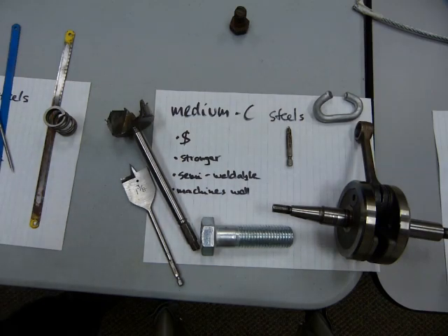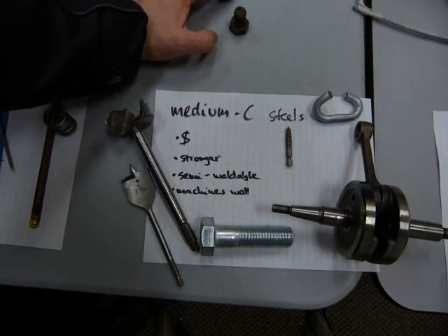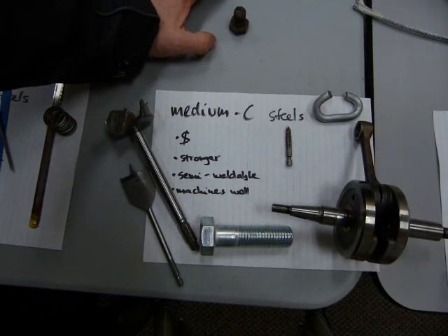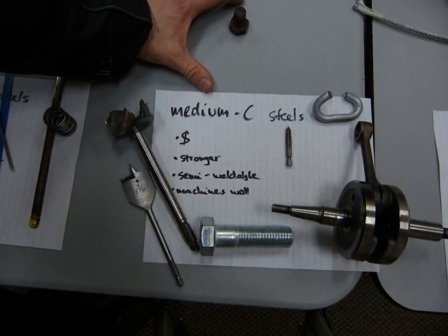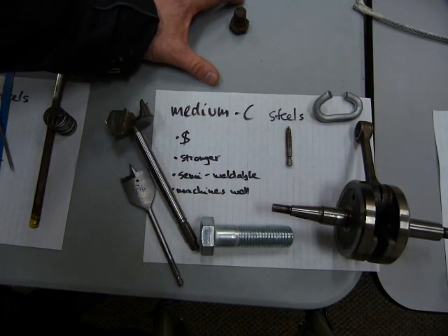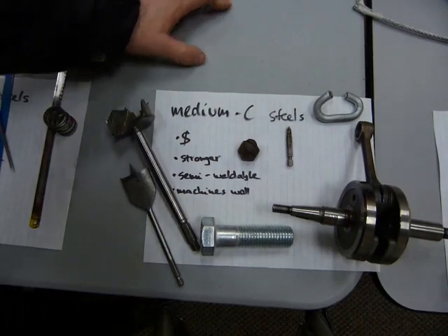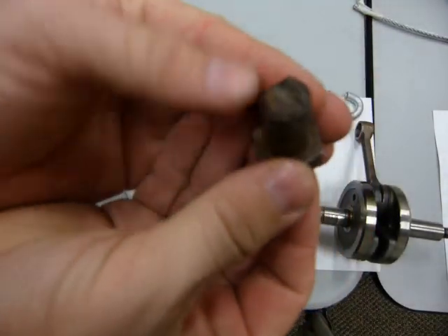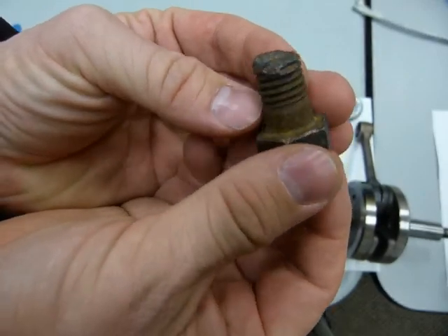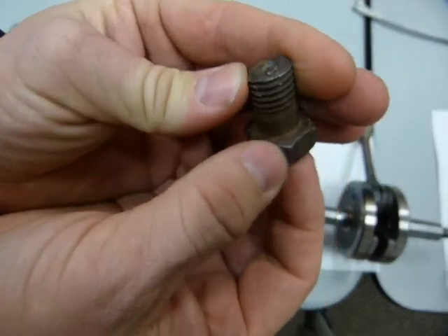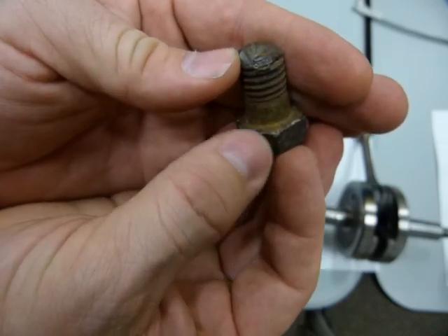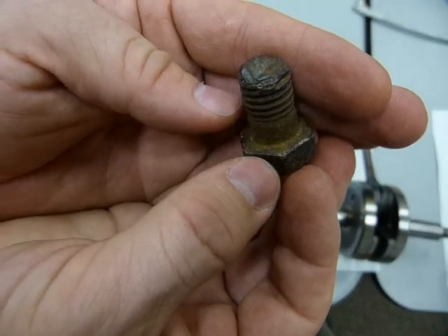Now, what happens when these fasteners, for example, don't comply with the precise chemical composition that's specified in those industry standards, is that you have substandard materials. And this one failed, and upon a metallurgical examination, it was determined that its chemical composition doesn't conform to any known standards.